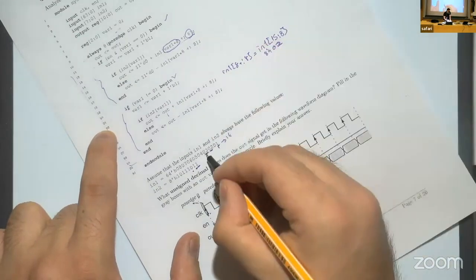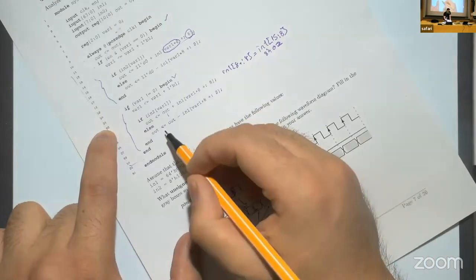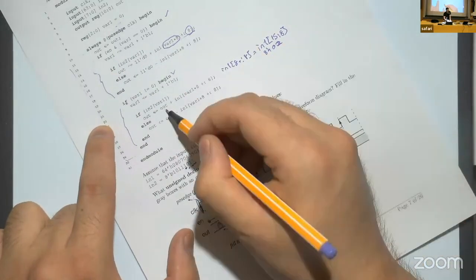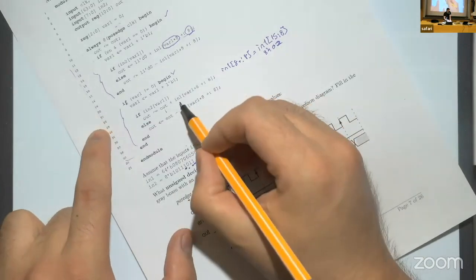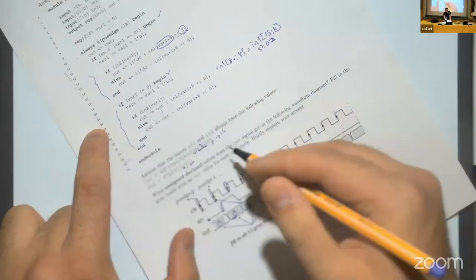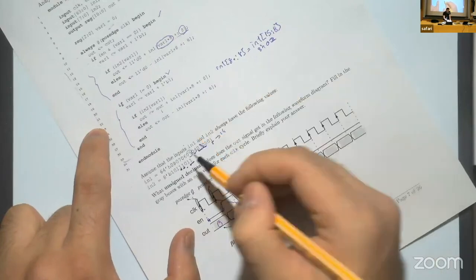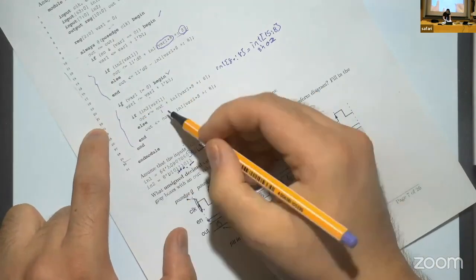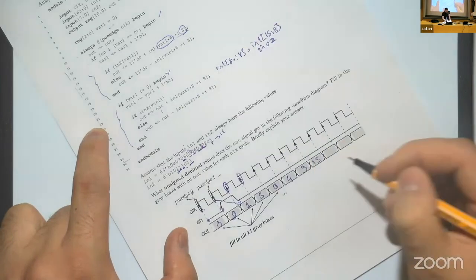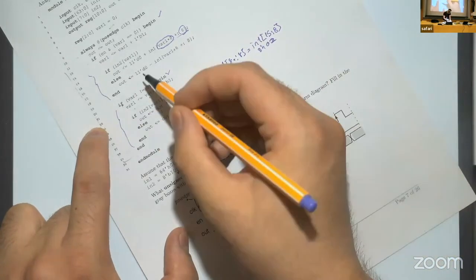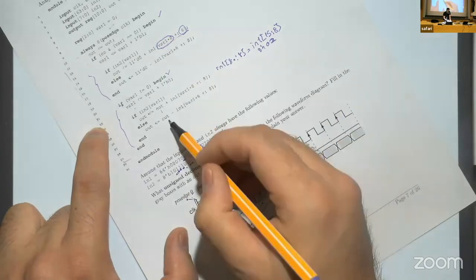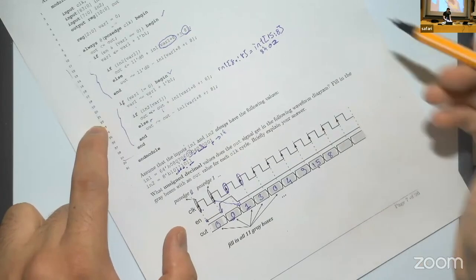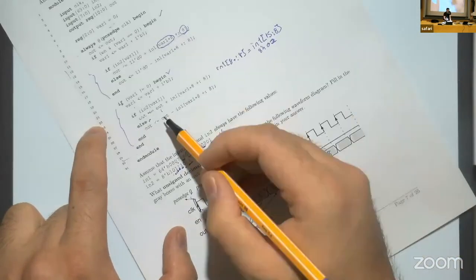Now in the next cycle, we execute the always block again, where var1 is now 6, and the in2 bit is 0. Which means that we need to perform subtraction here. It was 15 and this one is 7, makes it 8. Yes. Okay. Now we perform the same thing again, where var1 is 7. The 7th bit of in2 is 1, which means that we need to add. Sorry, var1 was 7, right?